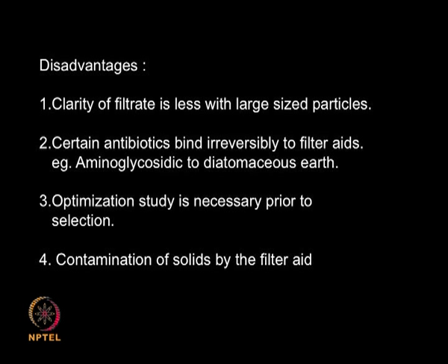For example, aminoglycosidic antibiotics may bind irreversibly to diatomaceous earth, so you are losing the product, so the yield goes down. So you also need to do some optimization study: how much filter aid I need to add, what should be the particle size of the filter aid, and so on.